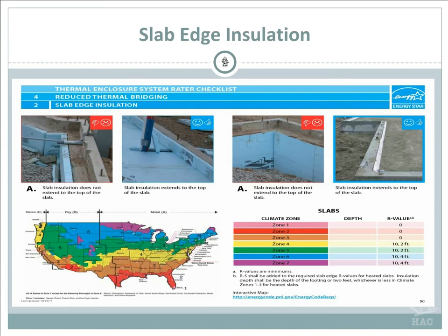These are pictures of slabs. Again, talks about different zones that you're in. If you're in zone 1, they don't need to be insulated. Zone 2, either zone 3, you don't really have to, but according to the IECC 2009, you have to insulate your slabs all over now. So it's not something that you have a choice. Zone 3 in our area, you definitely have to insulate slabs. And from there on, it just goes on.